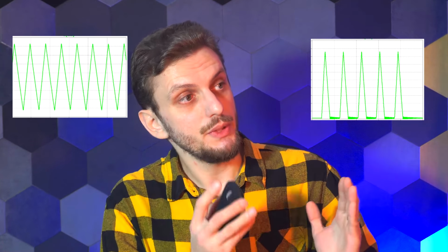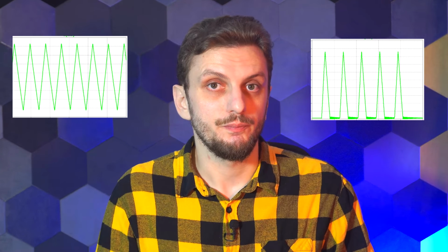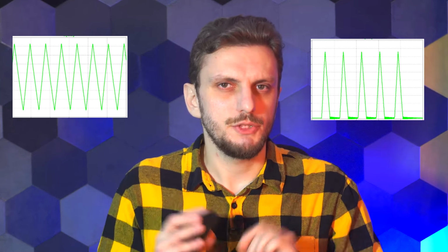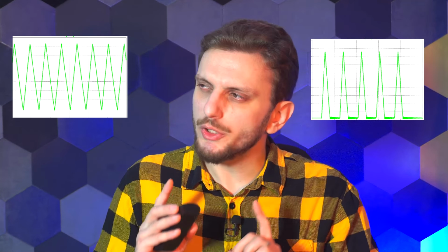So, long story short, conduction mode refers to how current is varying in the energy storage element in a switch mode power supply. In a basic converter, you can have a continuously variable current, or continuous conduction mode, which is a nice triangle waveform, or you can have a current that varies and then stops varying. So, discontinuous conduction mode. Now, these are some generic waveforms, but what more is happening in the converters? Well, if you're curious, then keep watching.